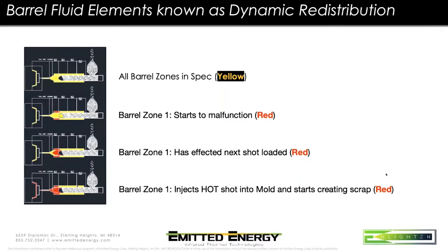So I'll be able to go through your whole mapping, knowing whether it's your thermocouples on your barrel or thermocouples through your manifold system, where those hot spots will be coming from, to point you in a direction of where to look. Not just tell you it's in your barrel, you got a problem, but that you got a problem with heater band number 3, zone 3. So these are some of the areas that it tells you right away what's happening.